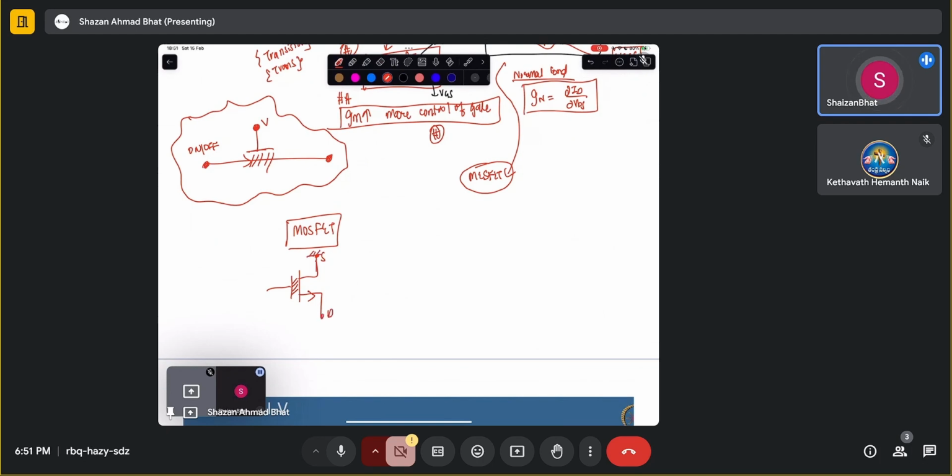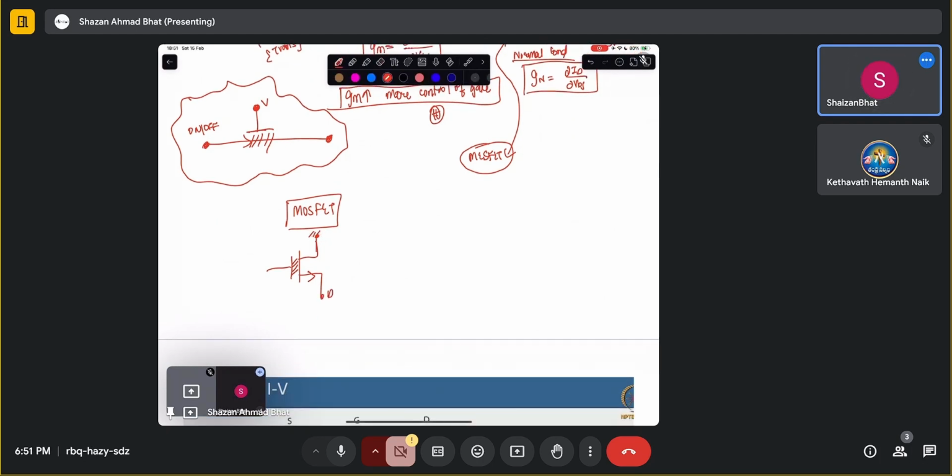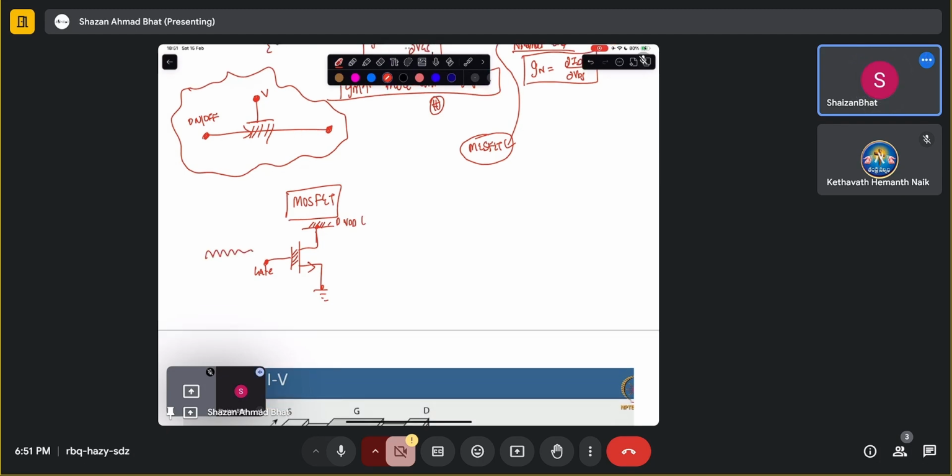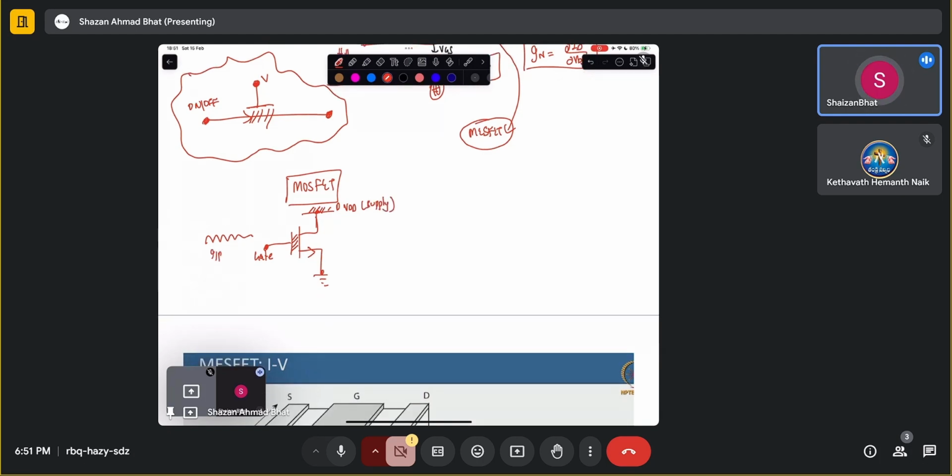And you apply some, let me draw it opposite here because it's symmetric. This is drain. You apply some VDD, constant voltage, and this is ground. This is the gate voltage, where you apply your input signal, and this is the supply you give, because you have to have the energy source. This is the input voltage. And the output you measure across this particular thing, which is also grounded. So this is V output.